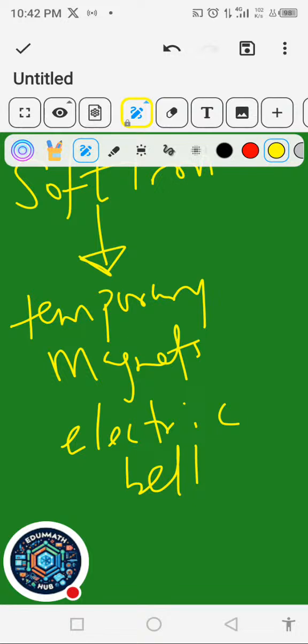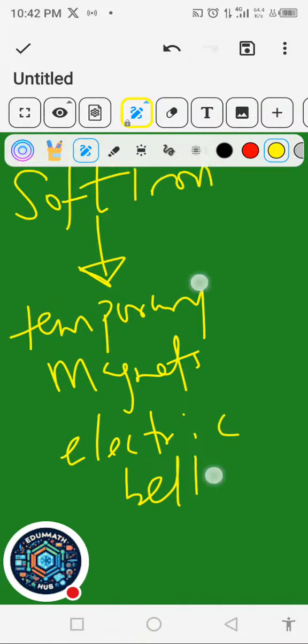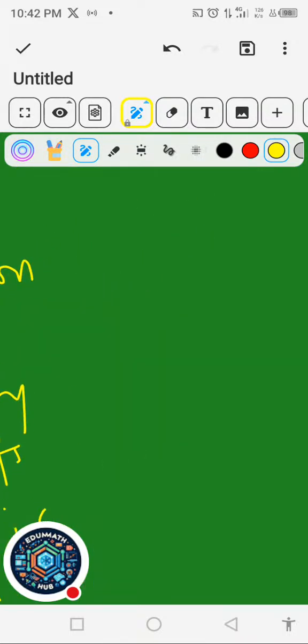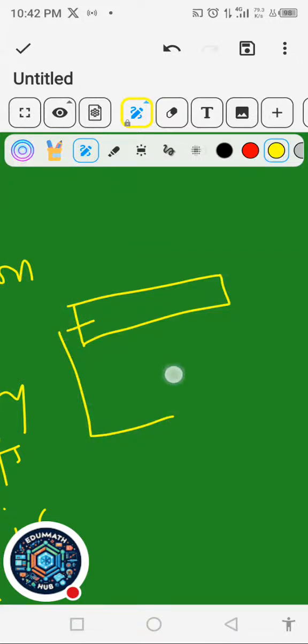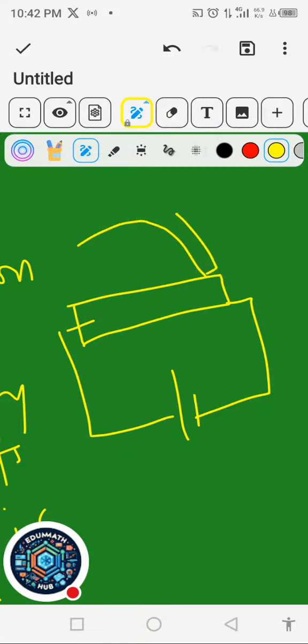If it's permanent, when you press the bell, the sound will not be like grrrr. The reason why you can hear that grrrr is because once you press the switch, the iron will become magnetic, so it will attract the striking bar, which is called the gong. The striking bar will hit the iron, so it will make that sound. Then it will detach later, because magnetism is not that strong. It will magnetize and demagnetize, going off and on.